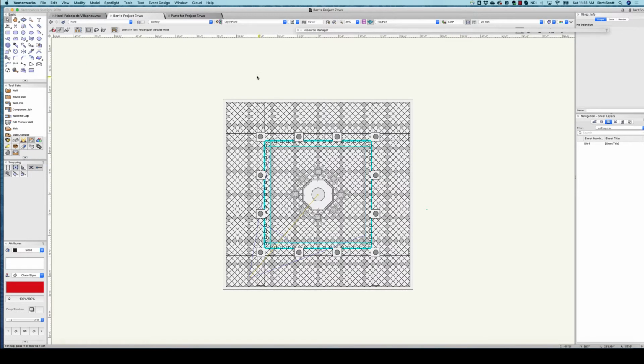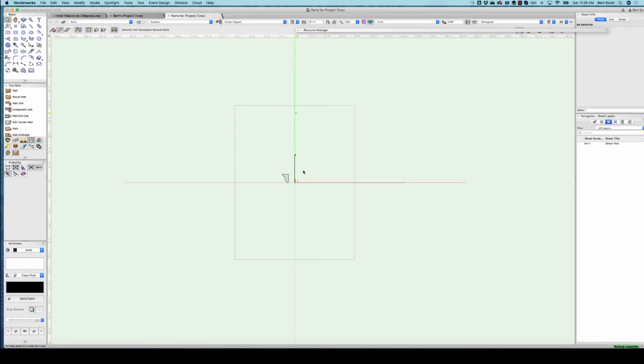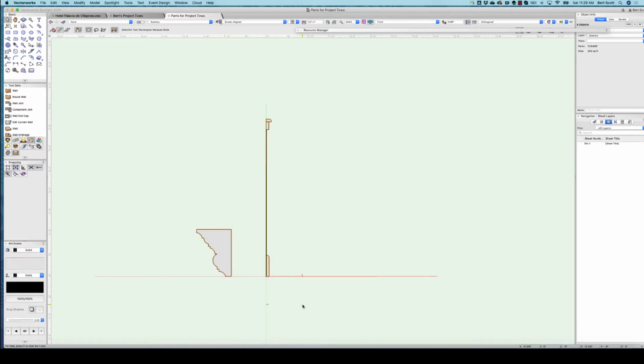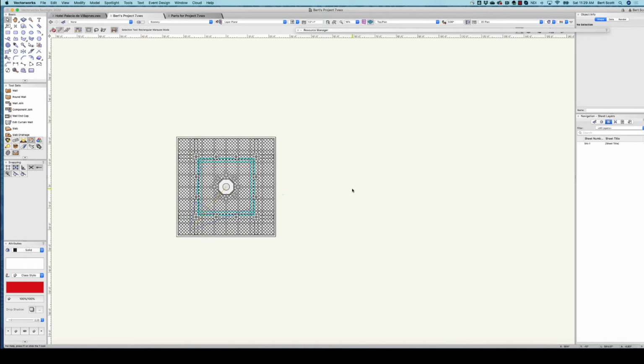Okay, to get started on the corbels, I think you've all probably done enough PDF tracing now. You get the point. So I've given you a file in WebCourses that is the shape of the corbel. So if you just want to open up that file, and you can go ahead and copy both of these things. This is the corbel shape, and then this is the wainscoting. Copy both of those and paste them into your Project 7 file. All right, there's step 1.